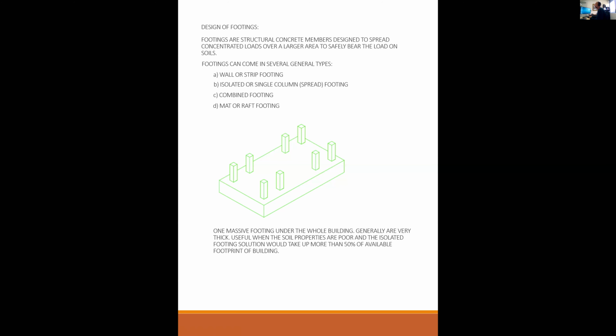But more importantly, when you design a slab on grade, you don't actually design it using ACI 318. ACI 318 doesn't cover the design of a slab on grade. There's a different reference for that, and it's just based on experience for doing warehouse floors and supermarket floors. It's really still just a concrete floor for the inside of whatever building you're doing.